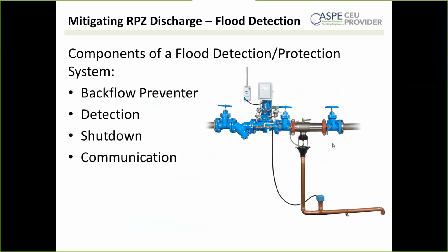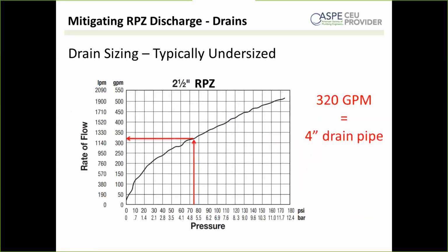Need the open area of the drain strainer to determine the flow in the head above the drain prior to flow. Yes, this is a good point. So I probably should have clarified this statement over here, 300 gallons per minute equals a 4-inch drain. That is an estimate based on a specific circumstance that I plugged into a drainage calculator.